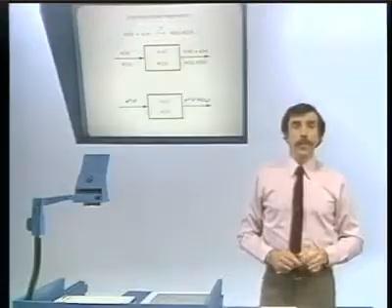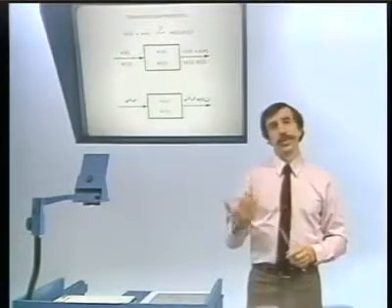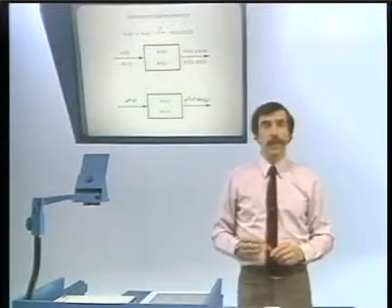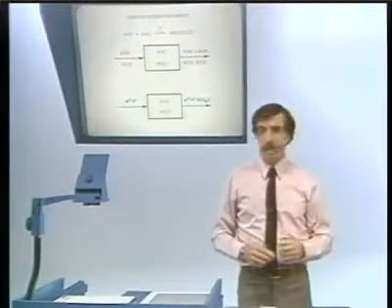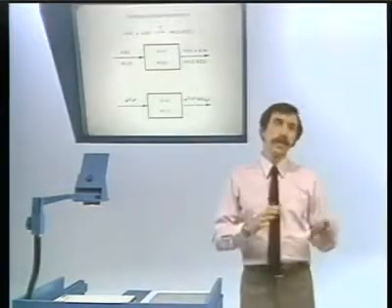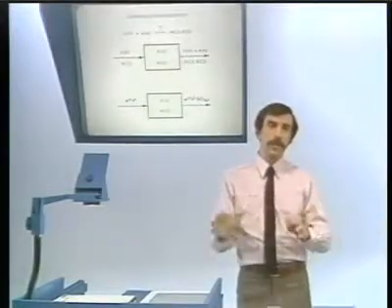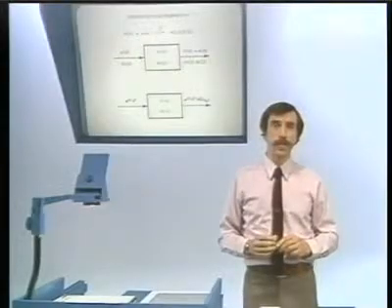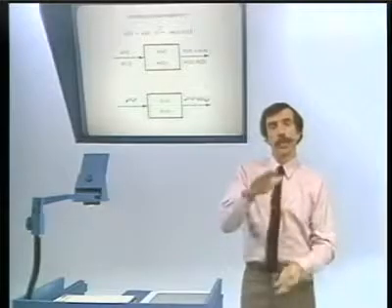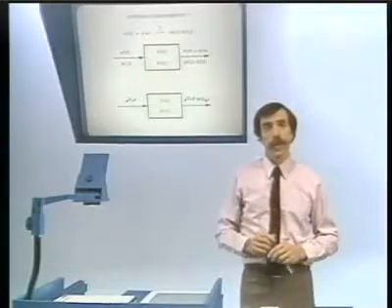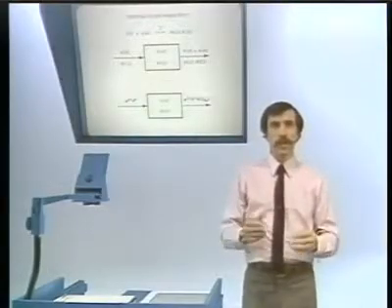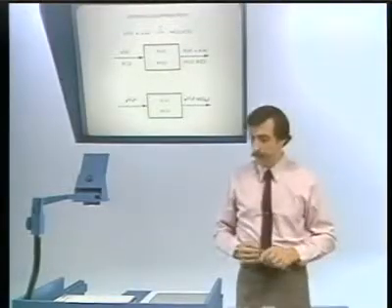Now, what we saw in continuous time is that this interpretation and the convolution property led to an important concept, namely the concept of filtering. The idea is that if we decompose the input as a linear combination of complex exponentials, we can separately attenuate or amplify each of those components. And in fact, we could exactly pass some set of frequencies and totally eliminate another set of frequencies.